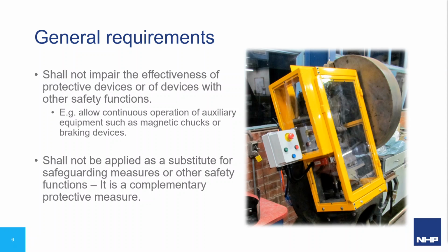Even after the e-stop is actuated, some auxiliary safety functions may still be required. For example, we may require the careful jogging of a machine to release a trapped person or allow the engaging or release of brakes, etc. Any additional functions allowed whilst the emergency stop is activated should be severely limited to only those required to reduce any further risk. They need to be carefully considered and addressed as part of a detailed risk assessment.